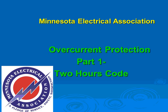The next one, I don't know how many of you have this. This is NFPA 70B. Anybody here ever heard of NFPA 70B? It says recommended practice for electrical maintenance. If you have a very good piece of equipment when you install it, do you think the same equipment is going to act the same way 10 years from the day of installation? Absolutely not. If you think your circuit breaker that you installed in 1990 is going to trip based on the same tripping function in 2013, you're wrong.